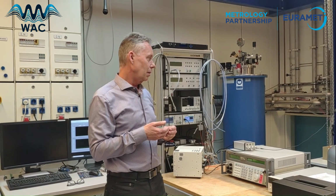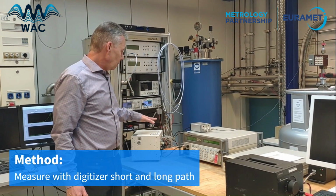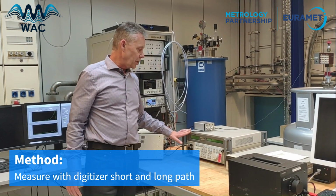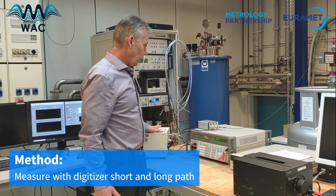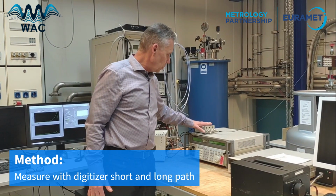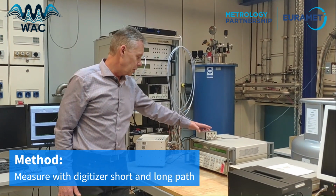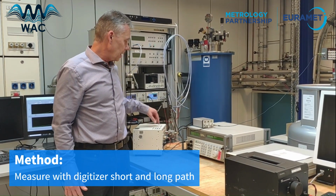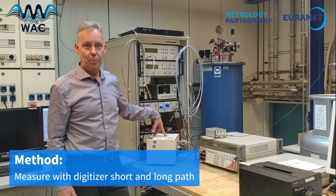So the idea of this method is to use the calibrator, to use the ADC or the digitizer, to measure the generator on a short distance by using the switch in between and putting a short on this output channel of the switch. So the signal goes via the switch directly to the digitizer with a short cable.